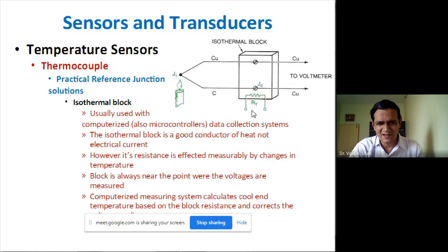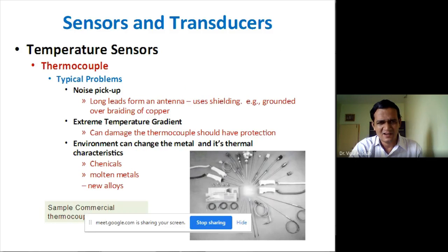thermocouple. Now we will see some different types of thermocouples, which were mentioned earlier. These are figures of those sensors which are utilized as thermocouples. Basically, you have to remember the signal should be received by you in a proper fashion. The lead should be such that it does not add its own resistance. Otherwise, the temperature you are measuring at the remote location is different. So you should have the proper selection as per the range of operation. For human body measurement, we can go for a thermocouple within the range of 0 degrees Celsius to a maximum of 50 degrees Celsius.